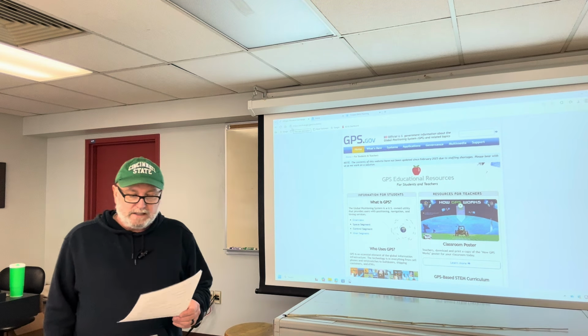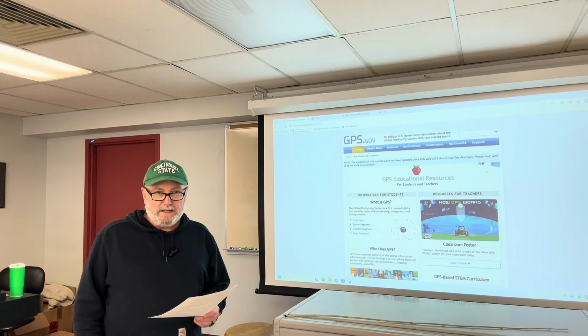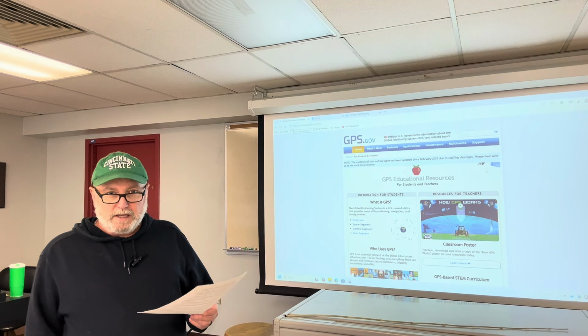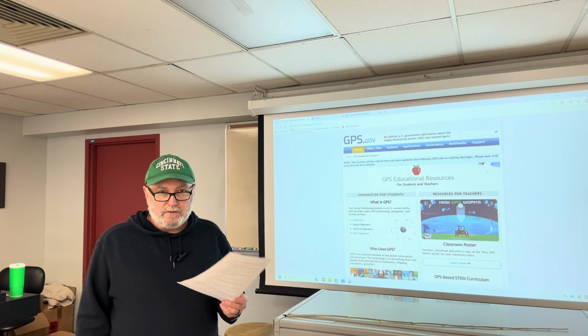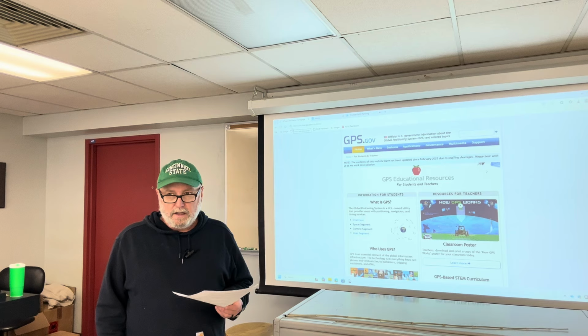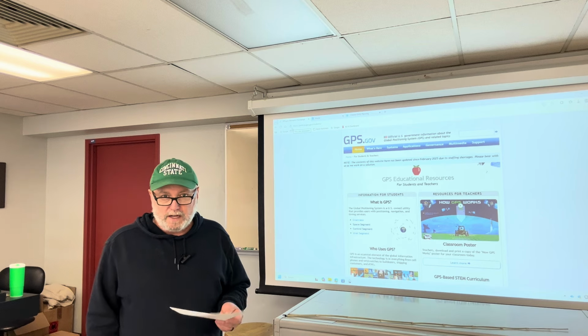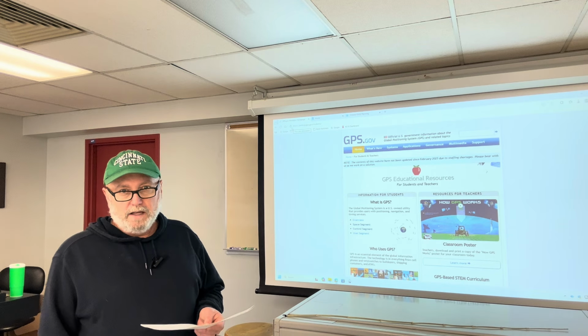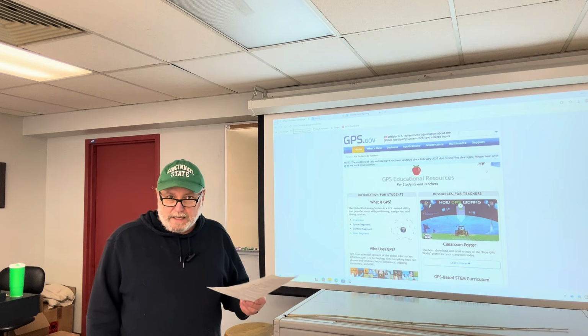Pre-planning with predicted DOPs is a core part of survey design. This will be something else we'll get into. There's another website that is free to access regardless of what GNSS systems you use. You can use it as pre-planning software to see what kind of conditions you'll be up against for a time. Again, these are planned.